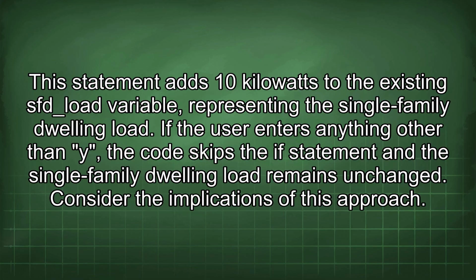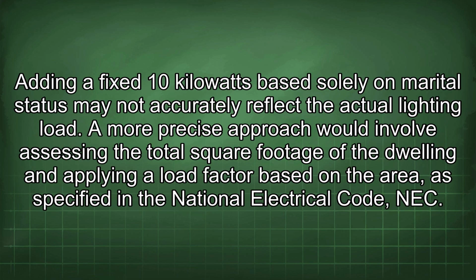If the user enters anything other than y, the code skips the if statement and the single-family dwelling load remains unchanged. Consider the implications of this approach. Adding a fixed 10 kilowatts based solely on marital status may not accurately reflect the actual lighting load. A more precise approach would involve assessing the total square footage of the dwelling and applying a load factor based on the area, as specified in the National Electrical Code (NEC).